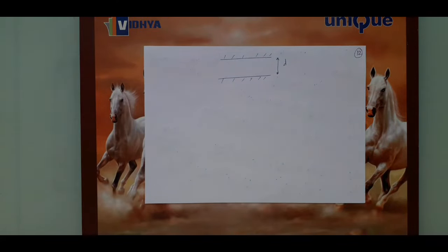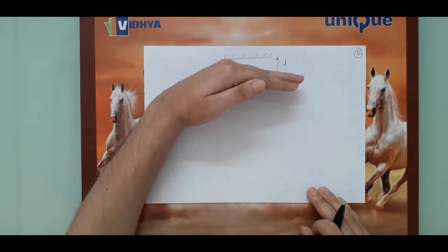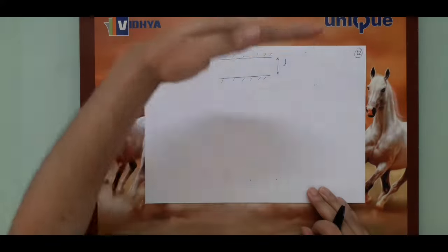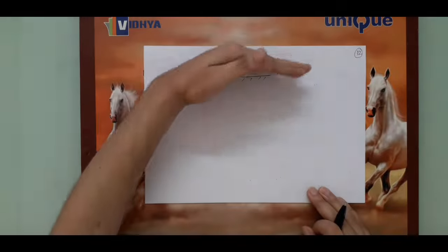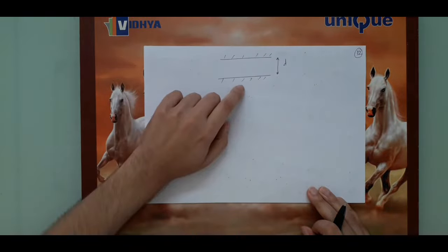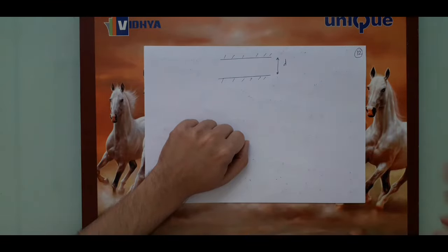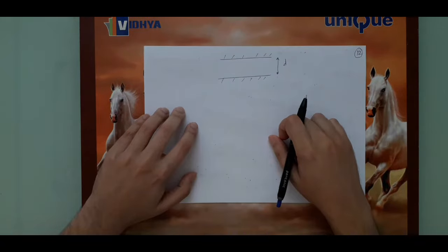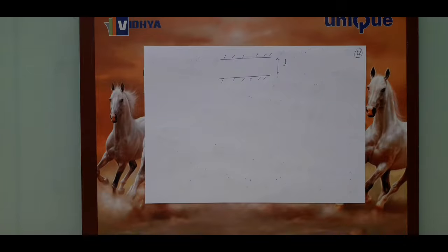Fair enough? Our analysis so far was that we had started off with one surface, and then we had analyzed how the fields are behaving along the x direction, and then we had introduced one more conductor plate at the point at which the boundary conditions were again being satisfied, similar to the first conductor. But now somebody gives you a parallel plate waveguide structure already. Now you cannot play with d.